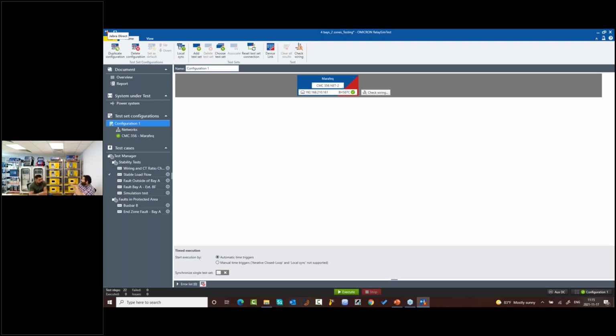This is the first scenario. The second scenario is that my substation has its own PTP time synchronization, which is already used in all relays. All modern relays have a PTP time source. At that moment, you don't need this source or the PTP switch, because you can use the time synchronization source from the substation itself. The third scenario, and I like it a lot, is that you can use the CMC itself as a grandmaster clock source. What does it mean? The master CMC will give the time signal for the other CMC. At that moment, you don't need a time source, because your CMC can do it.